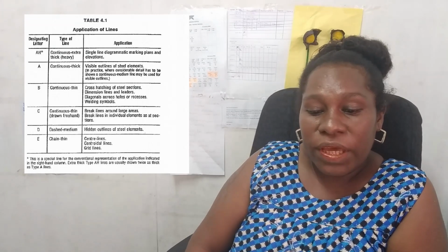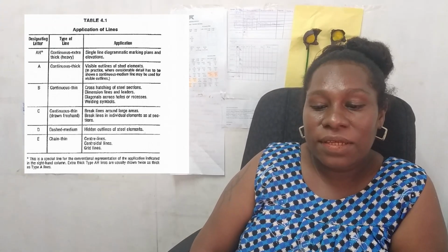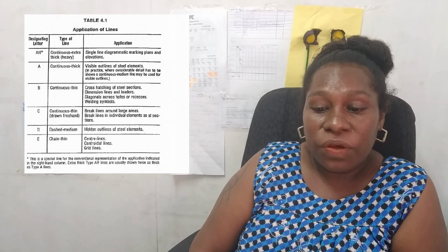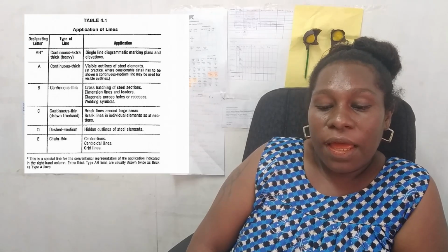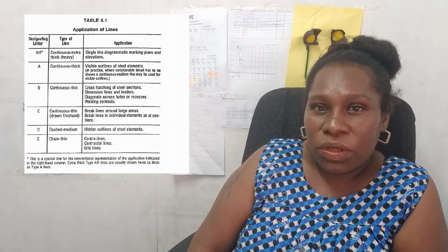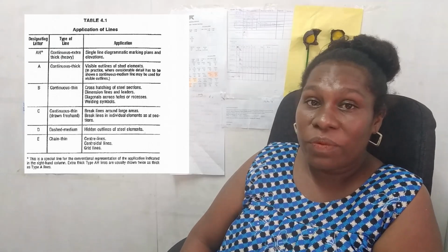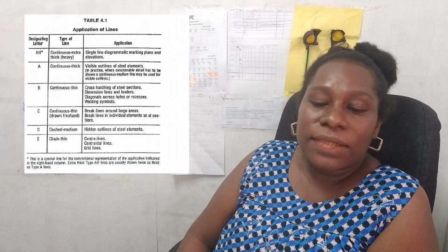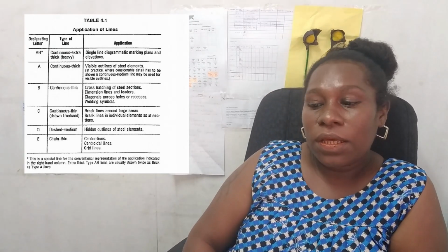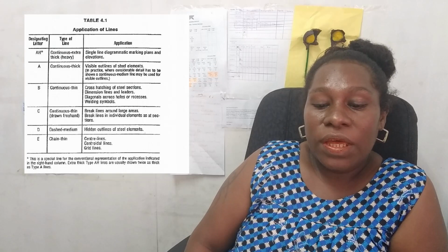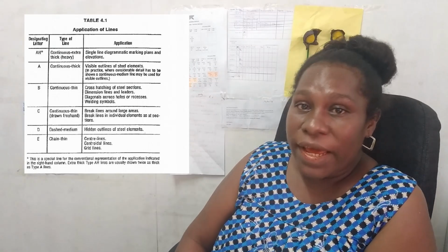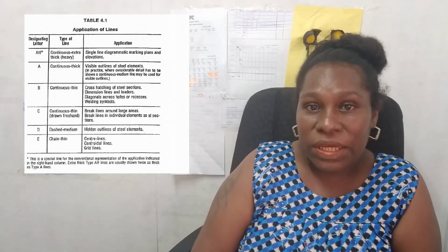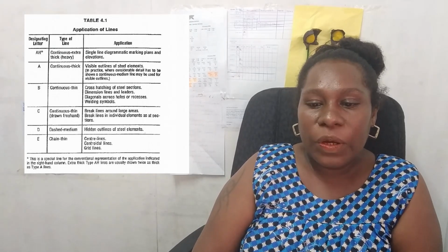In our case, we can create layers using these different types of application of lines, and then we can also use these when we want to print or plot, using different plot styles for different colors to give us these lines when we are printing them.